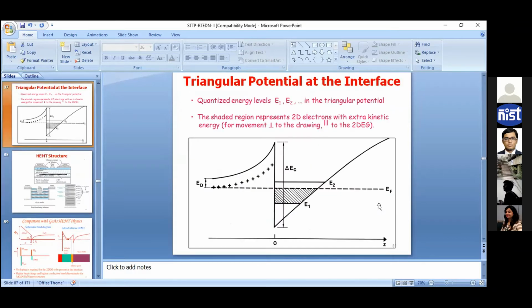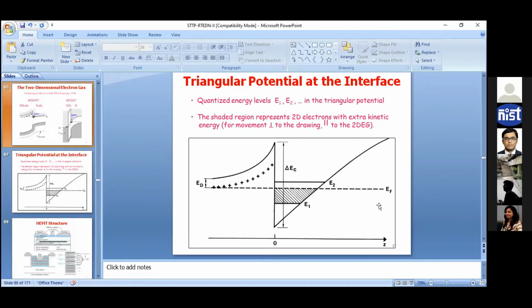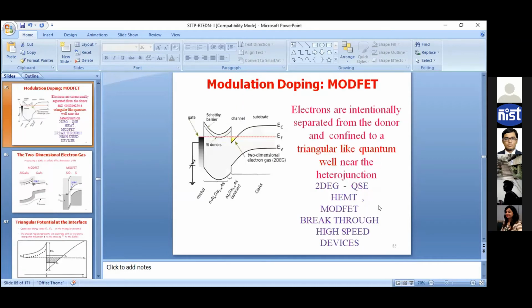Due to the difference in doping, we make one capital N and another small n. So N plus or N plus plus is the right notation. If you make it N plus plus, that means heavily doped. If it is only N, that is slightly doped.